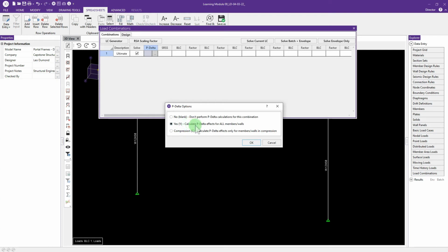Tension members, if there's an element that's all in tension, and P-delta effects are taken into consideration, then it actually increases the stiffness of the structure. And so for my purposes, I just want to focus on decreasing the geometric stiffness of the structure. All right, so I would use compression. But when you choose the yes option, you're implementing it for both compression and tension.